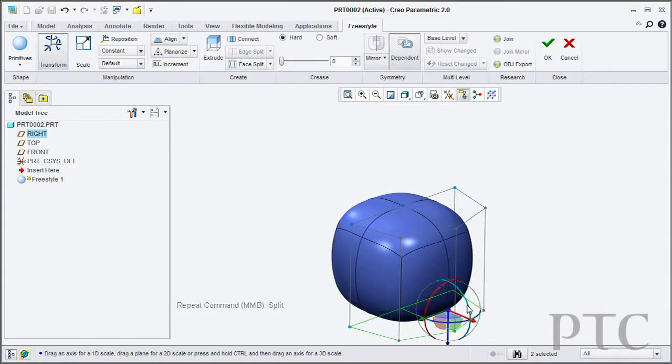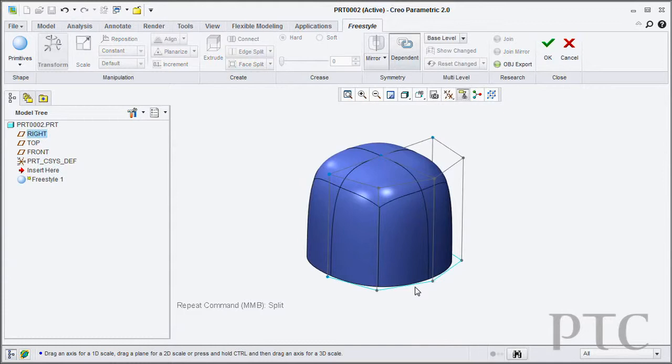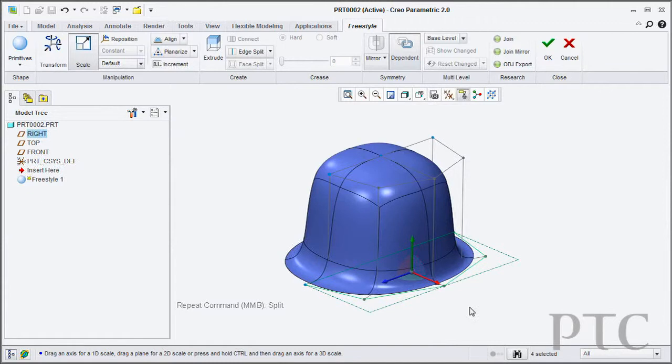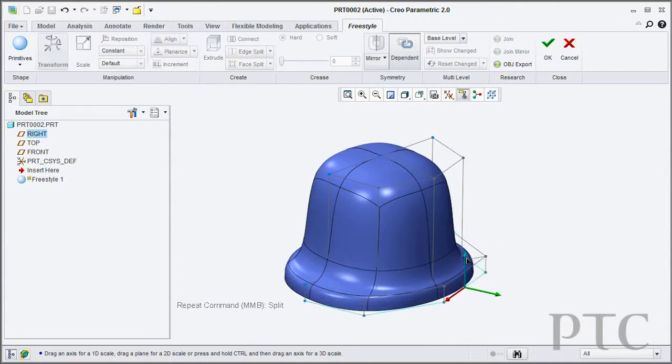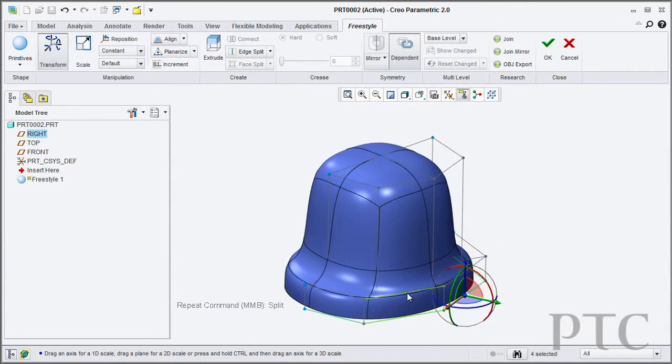If you pick any of the elements of the control mesh, a vertex, an edge, a plane, you will get a 3D dragger. This you can directly manipulate to modify your geometry. As you move the control mesh, the surface will automatically build high quality, curvature continuous, manufacturable surfaces for you automatically.